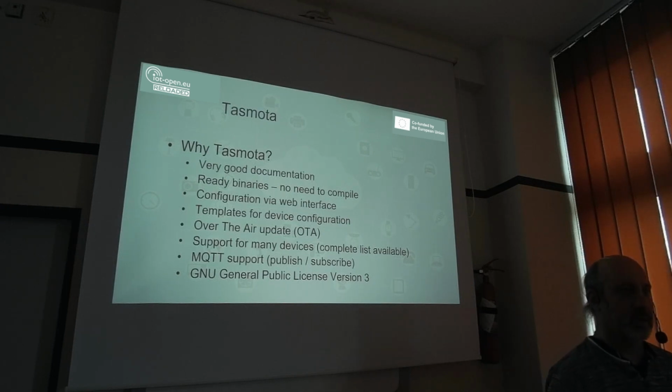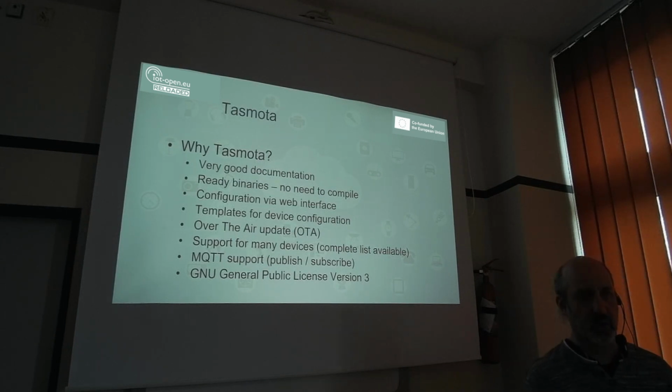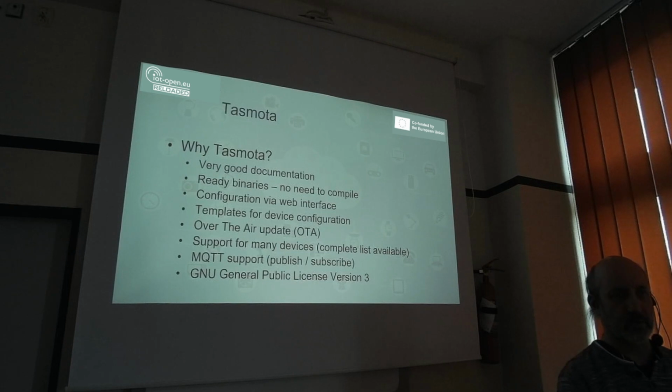Configuration of Tasmota is made via web interface, so while you upload the firmware to the ESP8266, you connect to it using your Wi-Fi network, and you can configure it fully. What is this device, what inputs, what outputs, what protocols it supports, configure MQTT, your network credentials, everything.